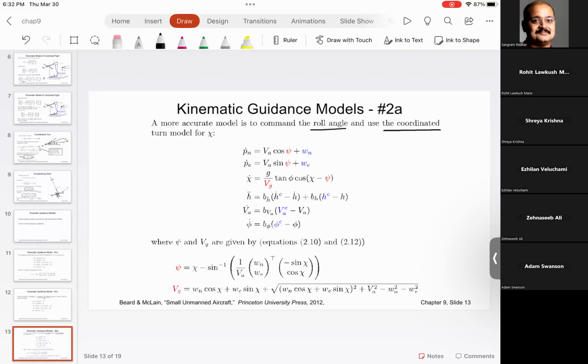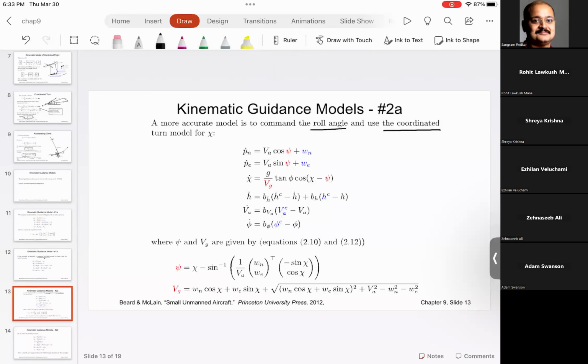And again, what we are doing is aggregating the equations that we saw earlier in this class, and putting them together just to come up with a better approximation of the trajectory or maneuver. So this is the kinematics equation that gets implemented on the autopilot. And I'm going to spend some time and show you how these autopilot equations are written for our MAV simulation. That will give you a better understanding of how these equations are implemented.